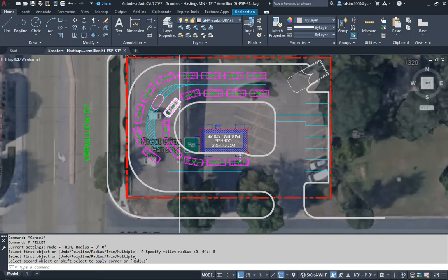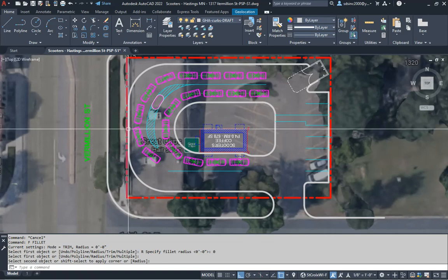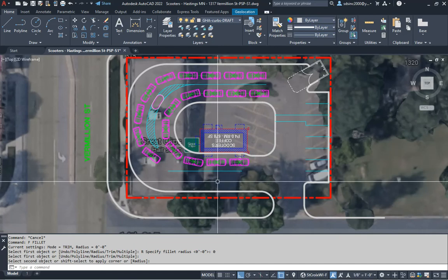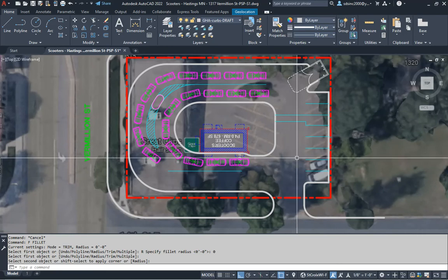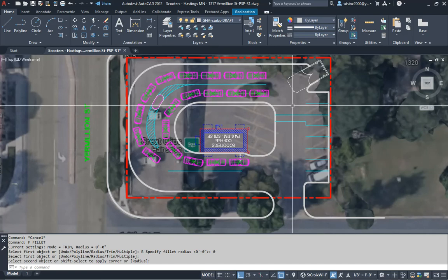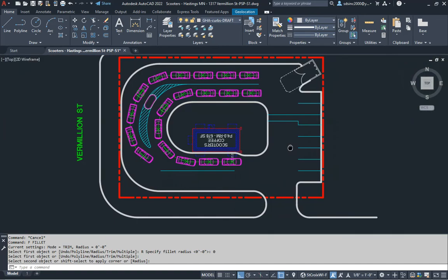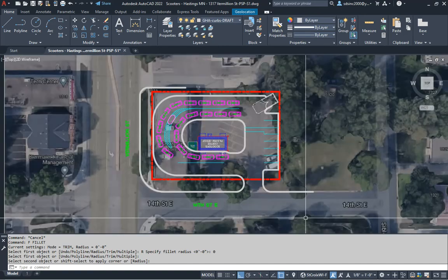When they're doing 20-foot radius turns like that, we'll widen this out to 16 feet here and here. And then we can get back down into 14 feet through here and 14 foot here. If there's parking on a straightaway like this, we would bump that to 16 instead of 14. And then, as we said over here, since we've got two-way traffic, 24 feet, and that gives us the ability to do 90-degree parking. So this is basically where you would stop the draft.